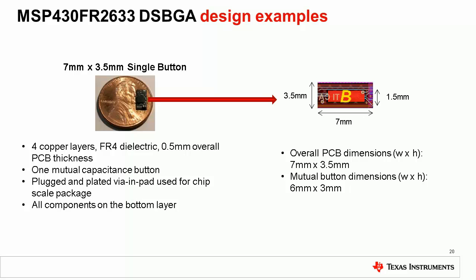The one thing I'll clarify for people today is that the Captivate solution isn't Q100 certified. If you had a Q100 requirement, TI does have other solutions, like our FDC capacitive sensing solutions for Q100. So there's a wide range of capacitive sensing solutions, whether you need the full automotive qualification or not. If it's not a requirement to have the full Q100, then a solution like the one we're showing here in the small form factor could also be used. The DSPGA is really targeted at a lot of these industrial type applications, but very similar from a moisture sensitivity perspective.